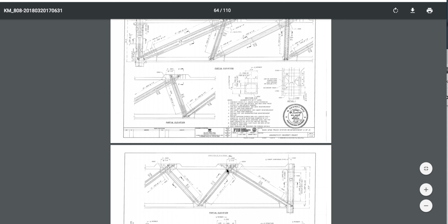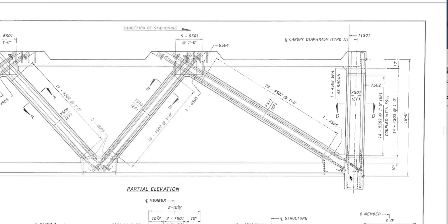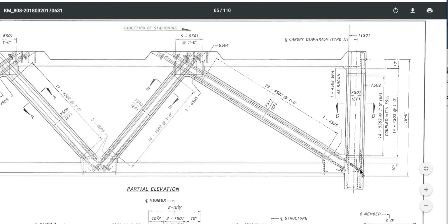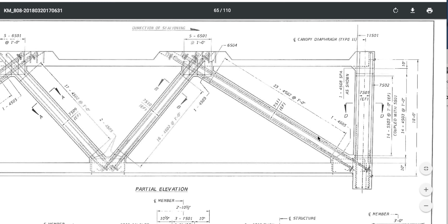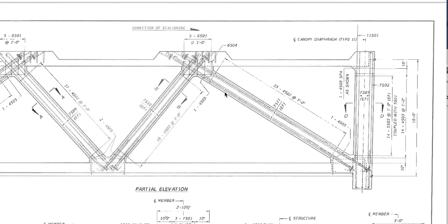Consequently, the interaction of this member here was able to pull, and across the steel here was able to lift this up just to a degree where it re-anchored, where it stopped, because the anchor was still in here and this bar was not fully denutted. I like that, denutted. And it re-grabbed, and that's why we see a stop in time again. The new equilibrium was established, and that's why I use the term equilibrium, so you guys can understand. The new equilibrium was established at that time.